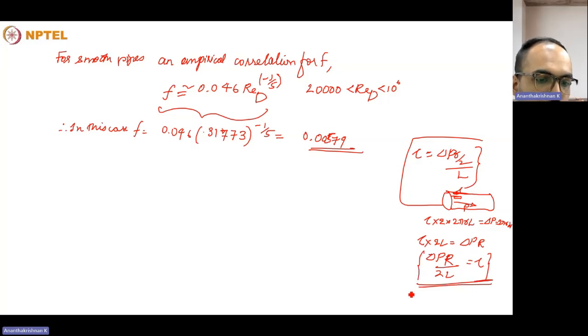So in the Hagen-Poiseuille flow, we know the value of delta P. We can actually find it from the fanning friction factor as well. We know that the skin friction coefficient will be equal to shear stress divided by half rho u infinity squared. So using the skin friction coefficient that we have seen, we will calculate it as well.